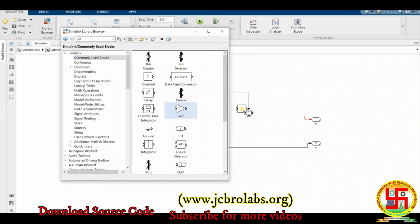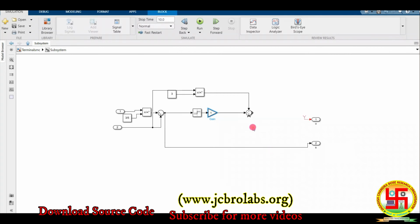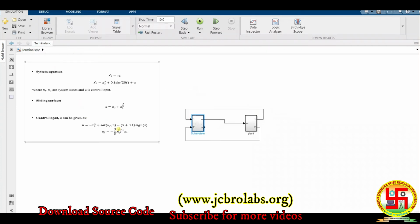So we'll take gain and we have here 5.1 because it is already in minus sign. And while using the sign function, we have to make sure that this zero crossing detection is always disabled. Now we have to make sure that this works, that is saturation of u_f comma 3, where u_f is this.